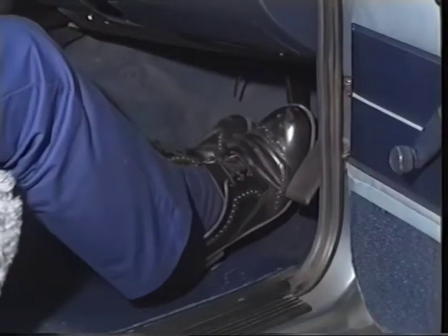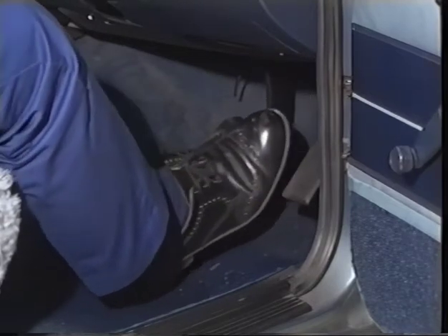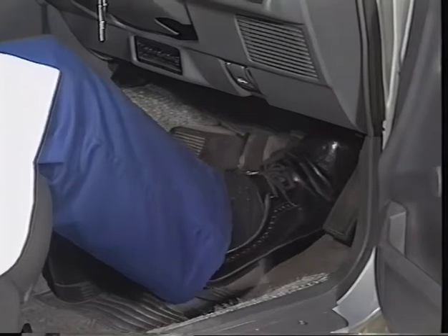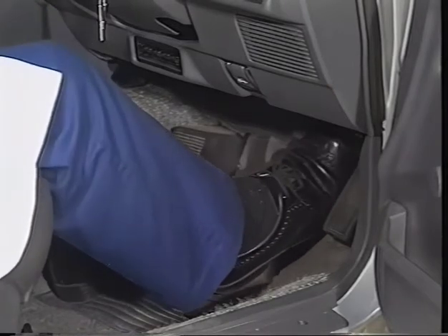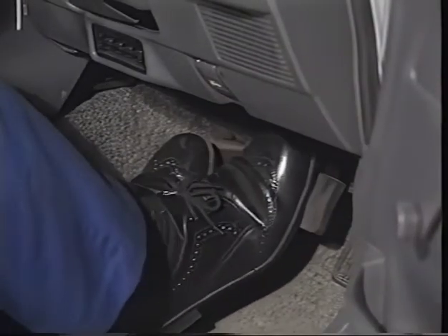In a previous video, we examined spongy pedals, which also suffered from excessive travel. A low pedal, however, can be easily distinguished because it exhibits one or two additional characteristics that the spongy pedal does not. The first is that whilst the pedal is low, it is still firm, with none of the sponginess of the previous complaint. The second characteristic is that on some systems, rapid pumping of the brake pedal may decrease some of the excessive travel, temporarily bringing the height back to somewhere near normal.